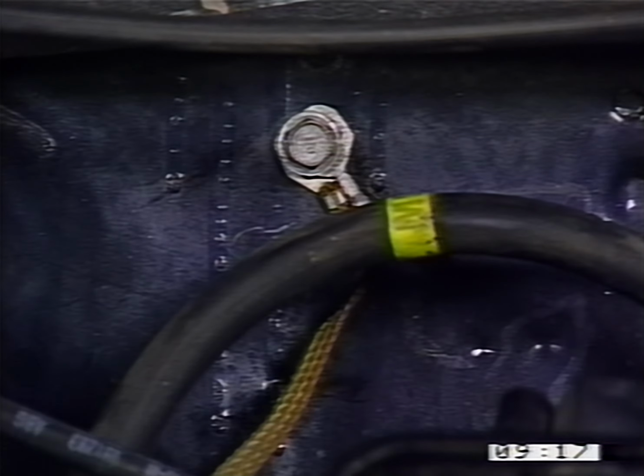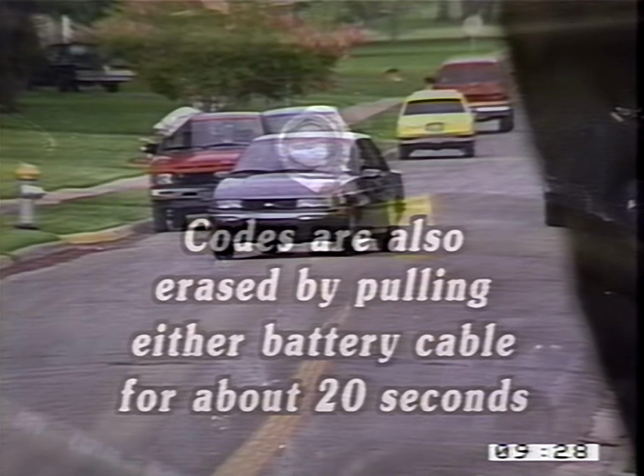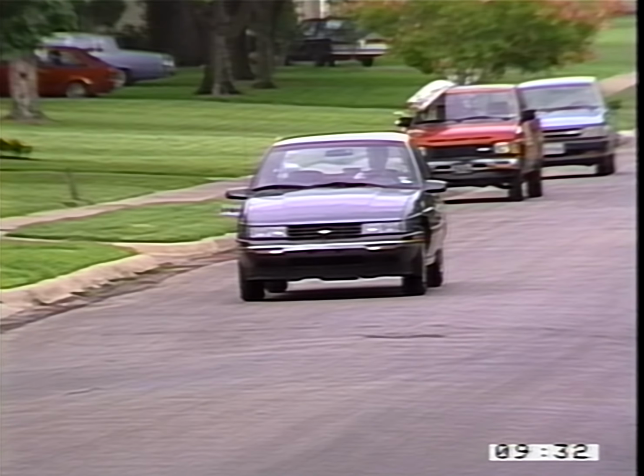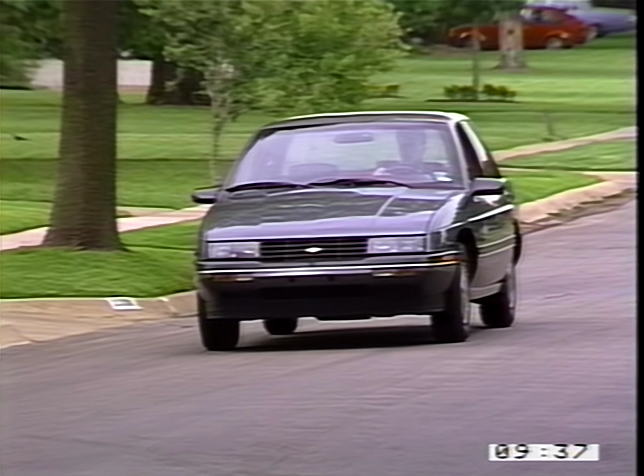The separate ECM ground connector found on later models can be disconnected at the battery. Codes are also erased by pulling either battery cable for about 20 seconds. When the codes have been cleared, the car is driven to check if the codes will reset. If after driving the codes are not reset, they should be considered intermittent.